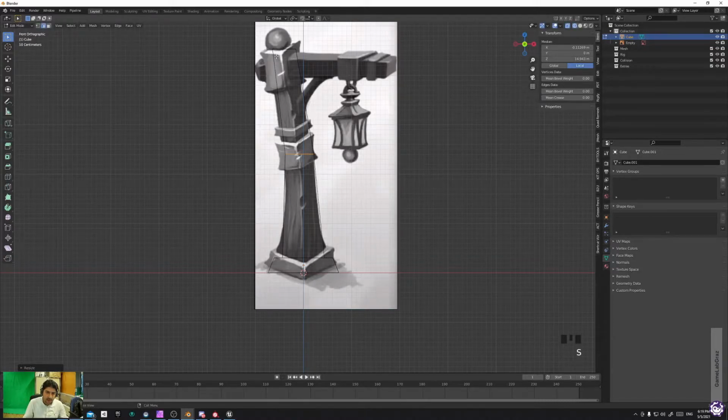And now you would like to give more curvature to your shape. If you have your loop cut and you bevel one edge, you can create several edges. In order to do the bevel, you can press Ctrl B and do the bevel. And if you scroll your mouse, you can create more edges. I see that after this, I'm not reaching the shape that I want, but it's no problem. We can use another tool and fix it.